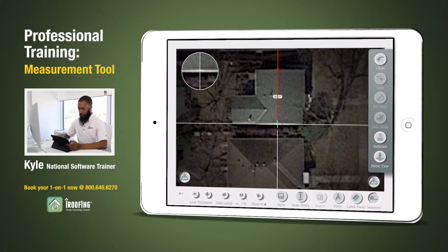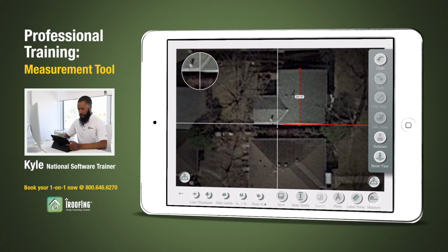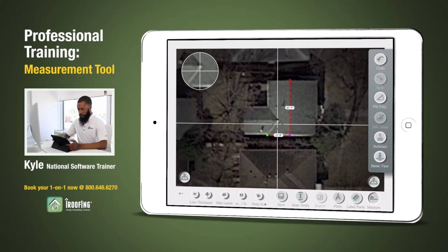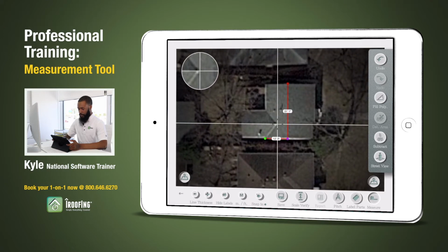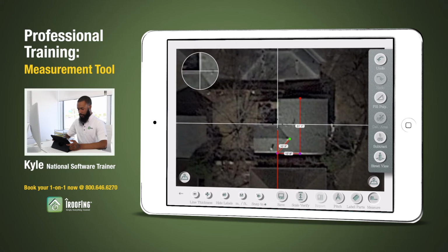Next, we will go down the rake towards the back of the house and stop where the rake and the valley meet for our dormer on the back. Place down our next point here. From there, we're going up the valley and onto the back of this ridge. Place down our next marker here. Then back down the opposite valley until we line up with our point at the bottom of the valley on the other end of the roof. Place down a marker there.